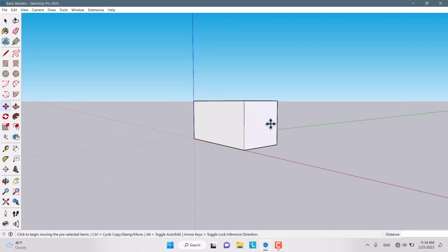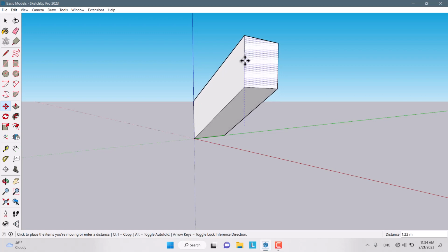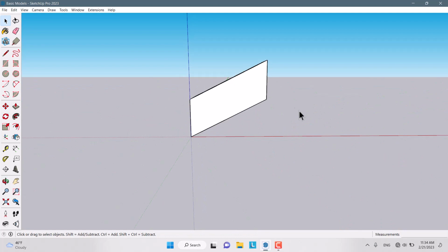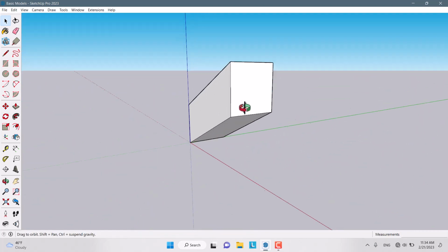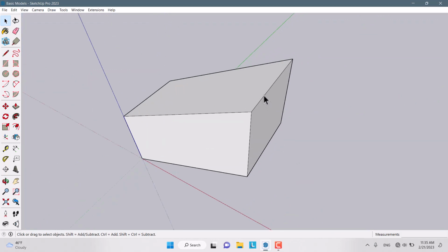And what happens if you move this face in the blue direction? Every place you want, you can select. For example, this midpoint: I left click on it, and now you can see if I change the movement to the blue direction, we have these types of shapes. For example, I want to move it in the blue direction for 1 meter. I type 1 on my keyboard and press enter like this, and we create these types of shapes, and we can do this job on the edges.